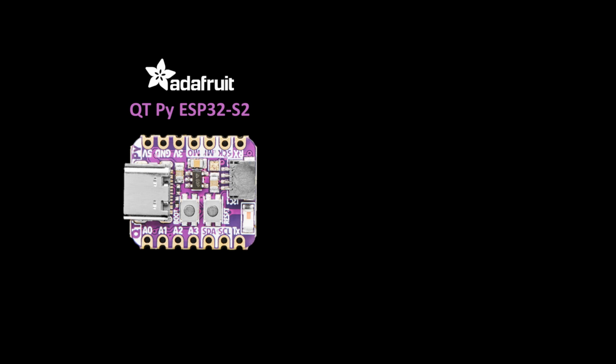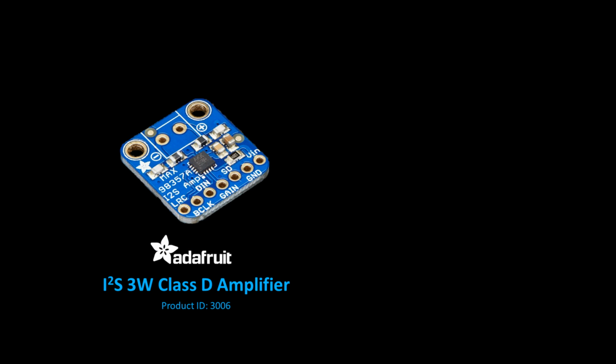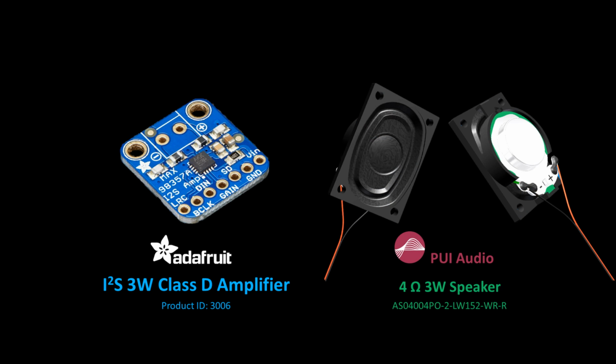In addition to displaying custom messages, a notification chime will also sound, which will require audio output. Currently, the QtPy ESP32S2 does not support the Audio I/O library or the Audio PWM I/O library. Therefore, I decided to use the same Adafruit I2S Amp that I used in my BLE restroom key tracker project. I'm using a PUI Audio 4-ohm 3-watt speaker.